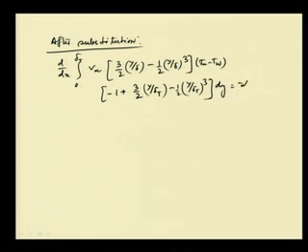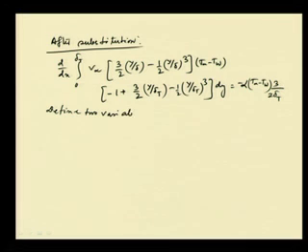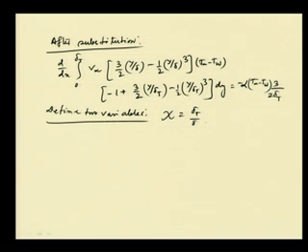This is equal to minus alpha into (T infinity minus T w) into 3 by 2 into delta T. Now, we will define two variables, like xi is equal to delta T by delta, which is the ratio of thermal boundary layer thickness to momentum boundary layer, the hydrodynamic boundary layer thickness, and say eta